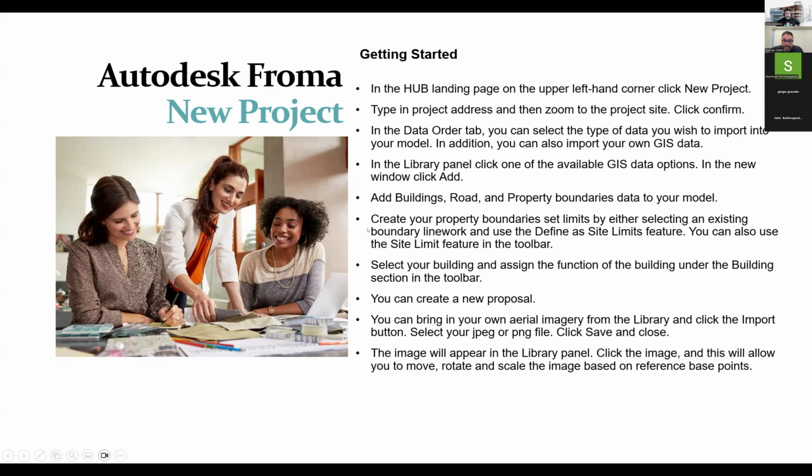And then I will say that you also can import models from InfoWorks, as long as it's, correct me if I'm wrong, OBJ and IFC files, right? Correct. Yep. And so you can also bring in SketchUp files. As long as you export as an OBJ file, you can bring that SketchUp model into it. So now there are some built-in tools in Forma where you can create your own building.